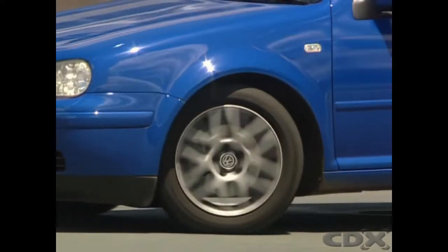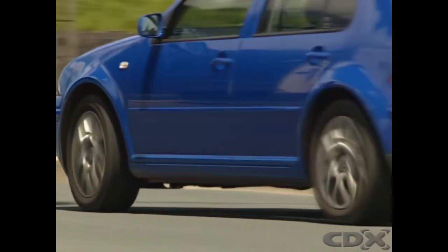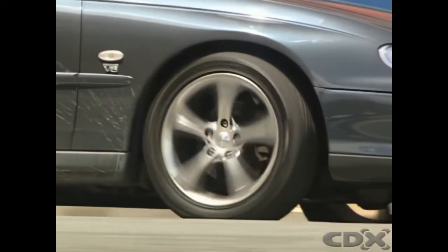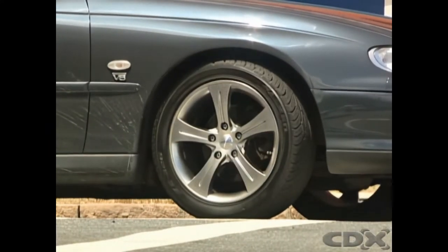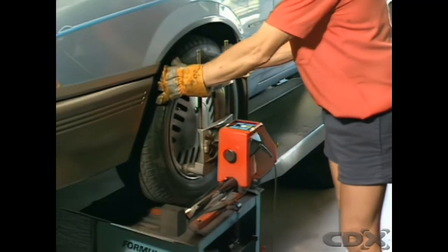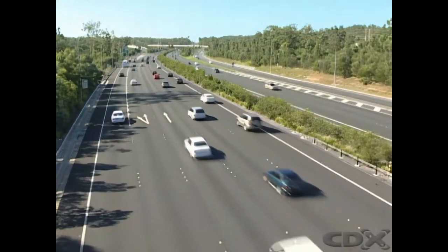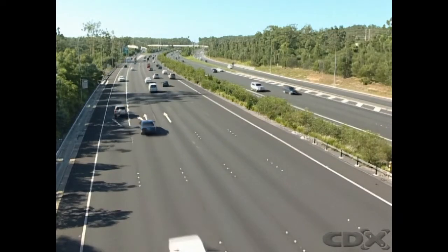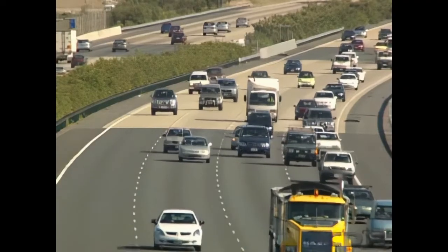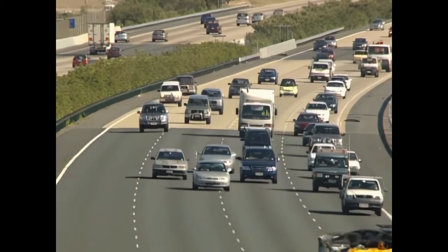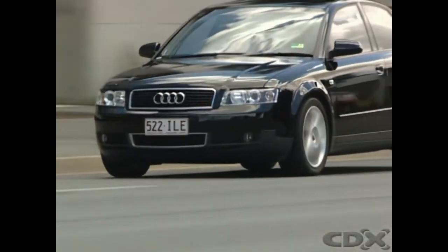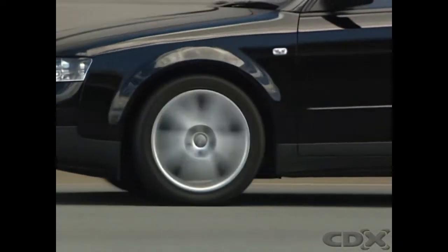On modern vehicles, however, tires are wider, but they are generally smaller in diameter. And large camber angles would produce excessive wear on the outer edges of the tires. The amount of camber is now reduced, so that most cars have what is called zero average camber to give long tire life. This is because when a vehicle is in motion, zero camber is difficult to maintain. Changes in running camber can be caused by road irregularities and load variations.